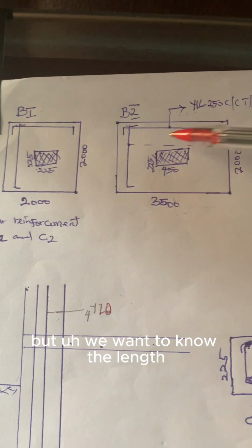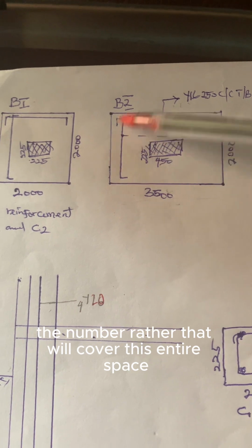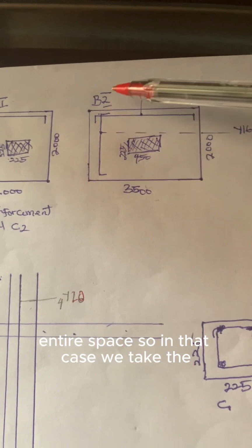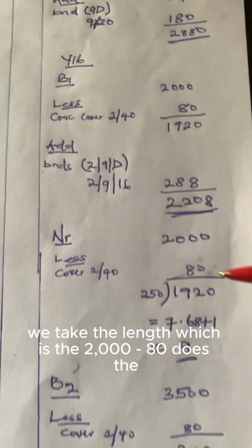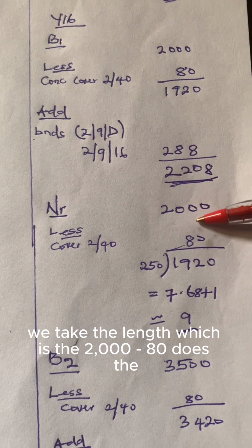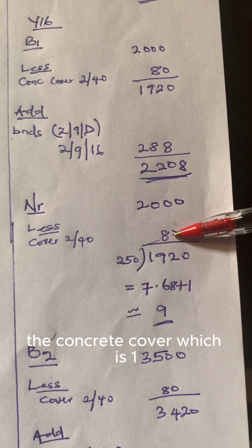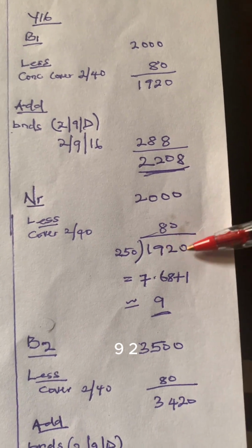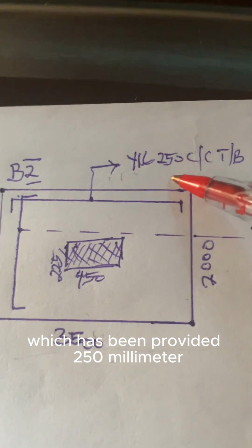So this is just the length of one, but we want to know the number that will cover this entire space. In that case, we take the length, which is 2000 minus 80 for the concrete cover, which is 1920. We divide it by the center to center space, which has been provided as 250 millimeter.